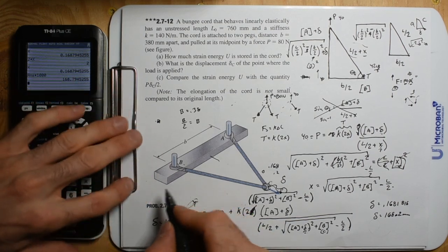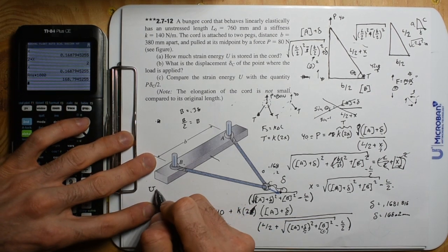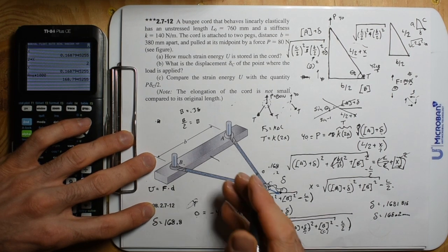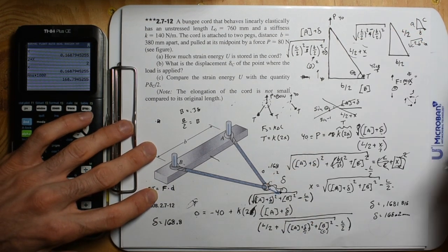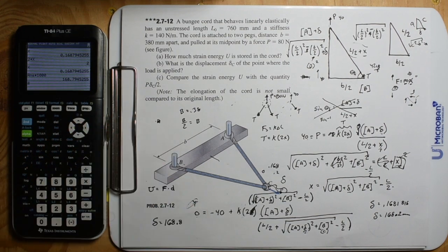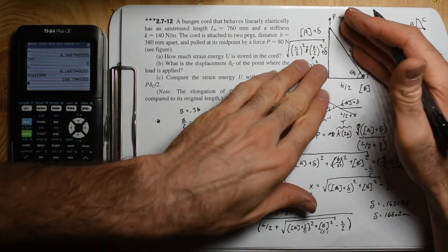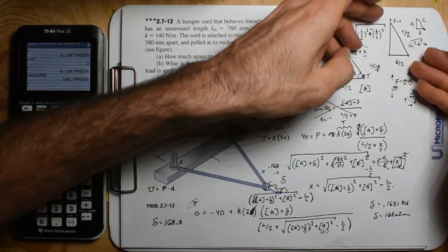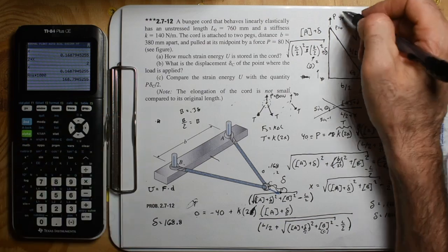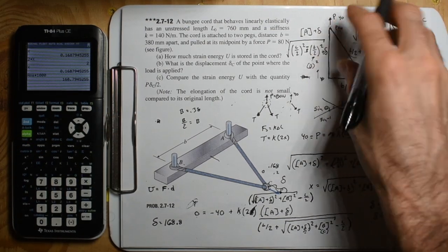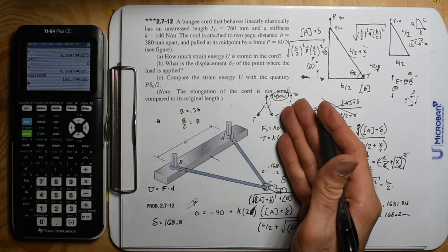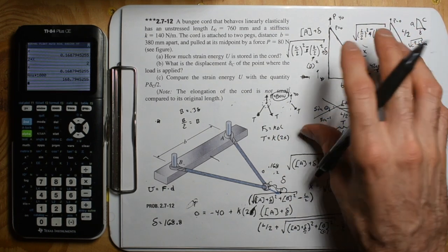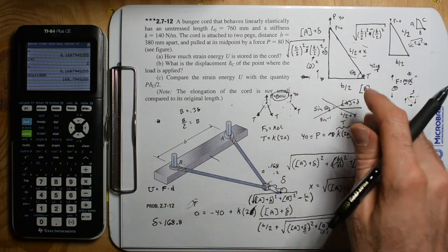And I'm not going to go over it 100%. I'm just going to say, well, we can. So energy is force times distance. And when you have a spring, it was back to that initial, and I won't bring up the literature again, but it's just like, yeah, this is the initial. P is equal to 0 right at this initial condition. And then P goes to a max of 80. So now you have a force that starts at 0, goes to 80. What's the average force between 80 and 0? Well, it's the max divided by 2.